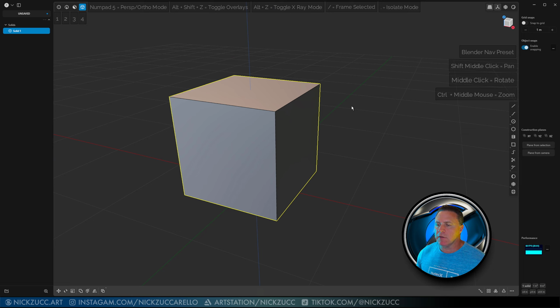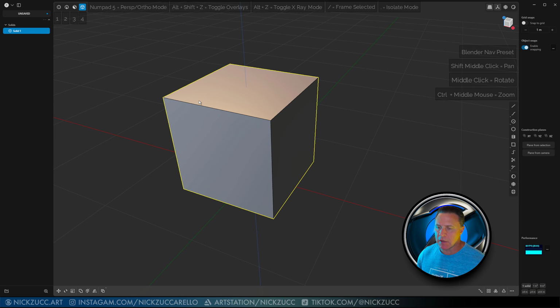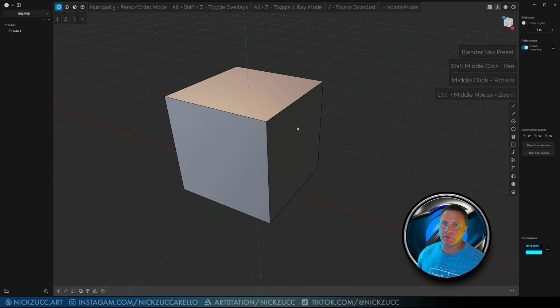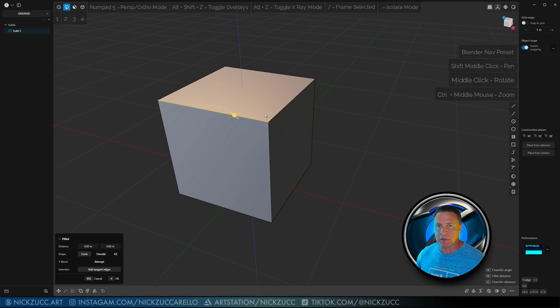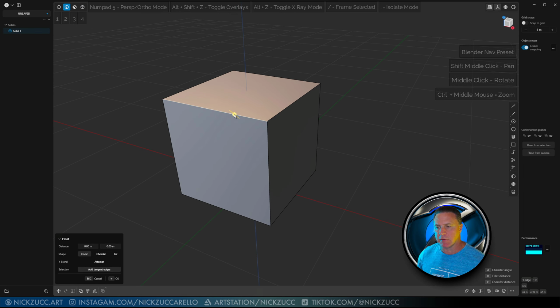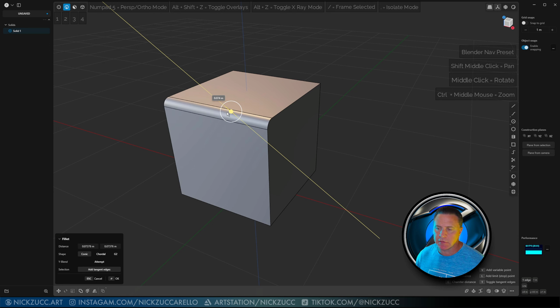Okay. The next thing I'll show you right here is that if you tap 1, 2, 3, and 4, the hotkeys for this, this is going to give you points. I can't actually select points within this model just yet. That's if we have some curves and we're working with curve data. But if we tap 2, we can get an edge. And you can see there's going to be a control that comes up and pops up immediately for us. And you can click and drag these two different directions, and that's going to either give you a fillet or a chamfer that you have on here.